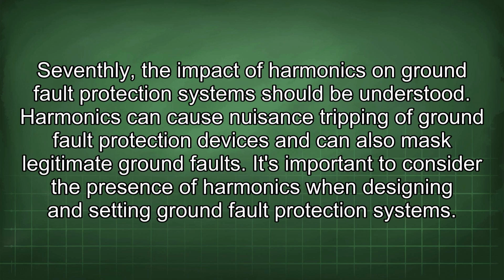Seventhly, the impact of harmonics on ground fault protection systems should be understood. Harmonics can cause nuisance tripping of ground fault protection devices and can also mask legitimate ground faults. It's important to consider the presence of harmonics when designing and setting ground fault protection systems.